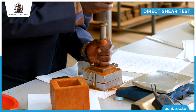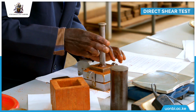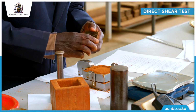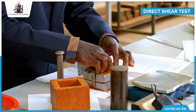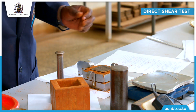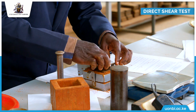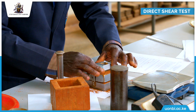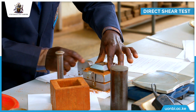Then on top, I'm going to position the other perforated plate, just like that. After ensuring that you have the top perforated plate in position, you place this other plate, which is supposed to assist in distributing the load on the specimen at the top.